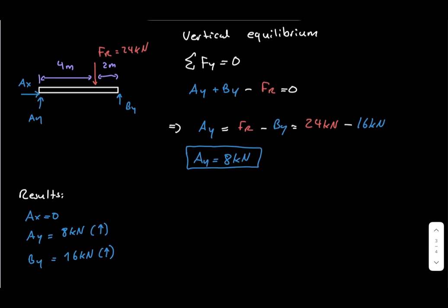Notice that the reaction at B is larger than the reaction at A. This makes physical sense because the load is concentrated closer to B. The most important lesson is that triangular loads are solved exactly like rectangular loads. The only differences are the magnitude of the equivalent force and its location. Once you know those two rules, the rest is just ordinary statics.